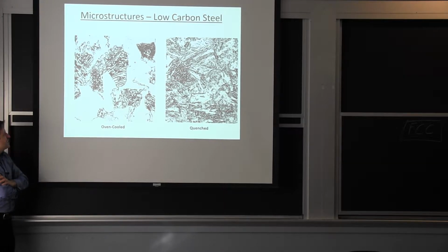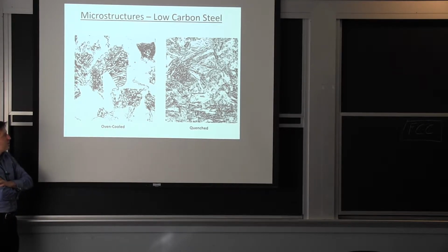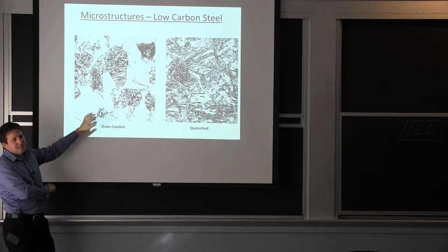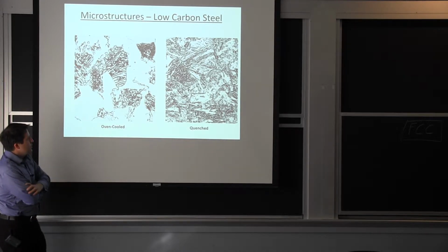That's very typical of structural steel. The steel that we use for car body panels, the beams, a lot of construction material. Everything that's going to be welded typically has this type of structure. If we're talking about a higher strength steel, you go through that quenching process.